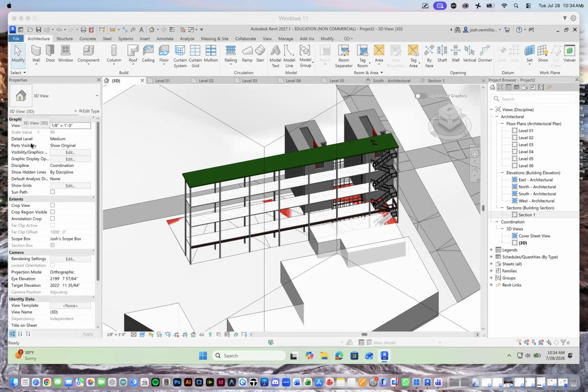Here we go. What you're looking at is a spine of hallway circulation going this way and this way, right? Let's say I'm just right here in this first, second, third floor hallway or corridor. What I need is, in case of a fire or some sort of emergency, two ways to get out.